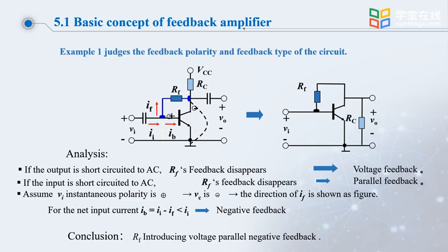Let's judge this RF's feedback polarity. Is it positive or negative feedback? First, its feedback type. By definition, as the internal circuit is connected, on the output side it extracts the entire voltage signal, and the input side is in parallel with the input, so it's a voltage parallel feedback. So is it positive feedback or negative feedback?